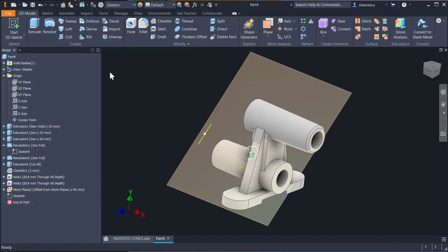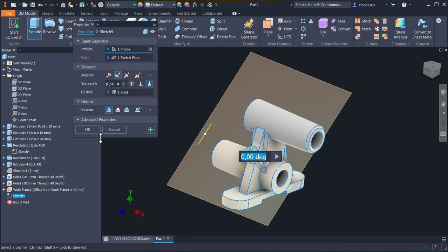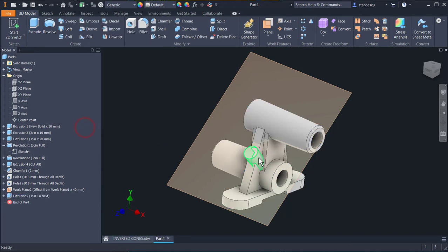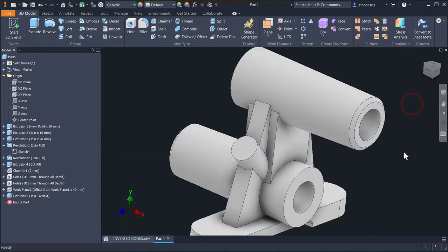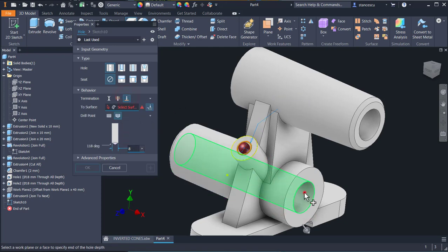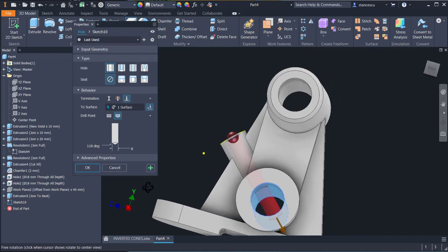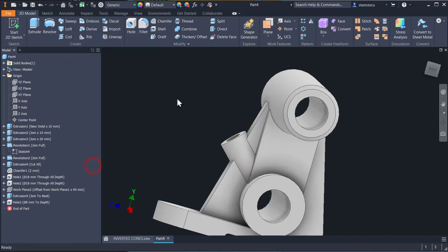Finish sketch, extrude to the part. Okay, this is the first extrusion, round extrusion. The hole is 8. This face, this center, 8, to this internal hole or surface. Okay.